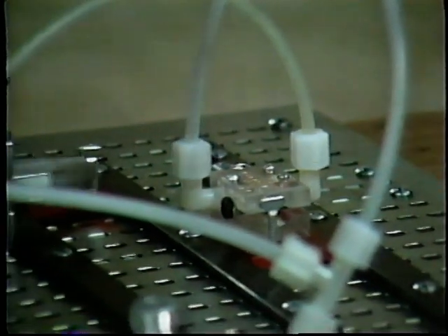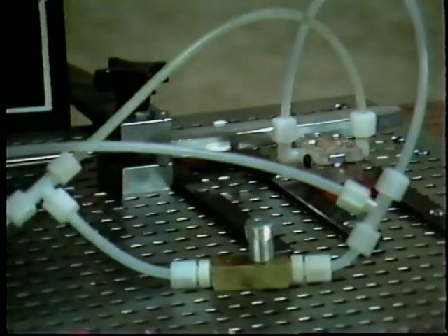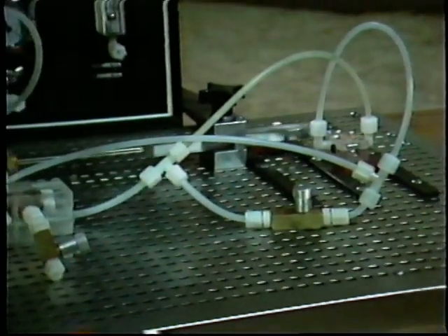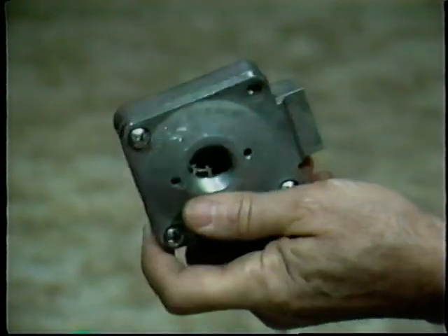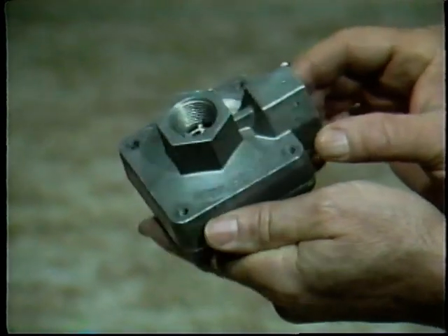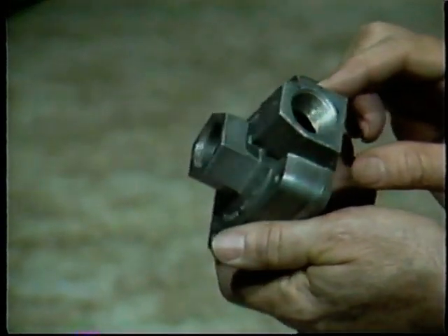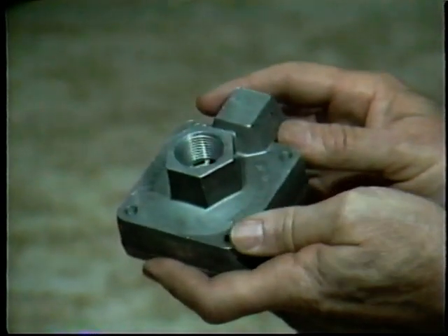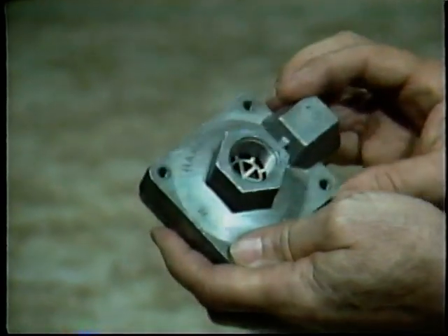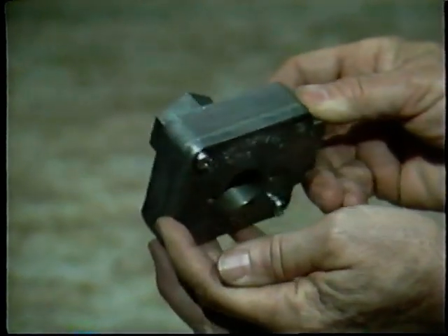As we said earlier, there are many circuits which could provide the same multiple speed control, but we selected this one since it uses many of the pneumatic components we have covered so far in this course. Before concluding this lesson, we should mention two other special purpose devices which are often used in pneumatic circuits: quick exhaust valves and silencers. Here is a quick exhaust valve. It is most often used with three-way or four-way directional control valves to increase exhaust flow, and its purpose is to speed things up by providing a shortened path for the exhaust to reach the atmosphere.